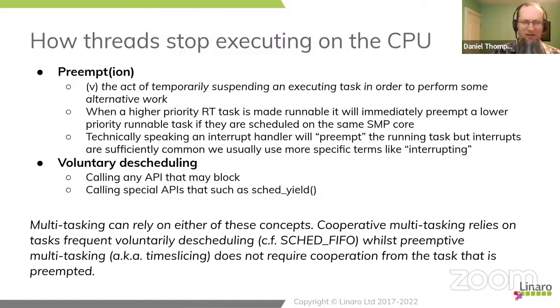So these are right back in the late 90s. And they all worked on cooperative multitasking, which sounds nice, but because everything relies on application cooperation, as soon as you get a bug, things fall over very quickly. So the dominant model for anything but kind of fixed purpose microcontrollers has moved over to this kind of involuntary preemption model. And that's quite important to understand because one of the concepts we're going to look at is voluntary preemption as a concept.